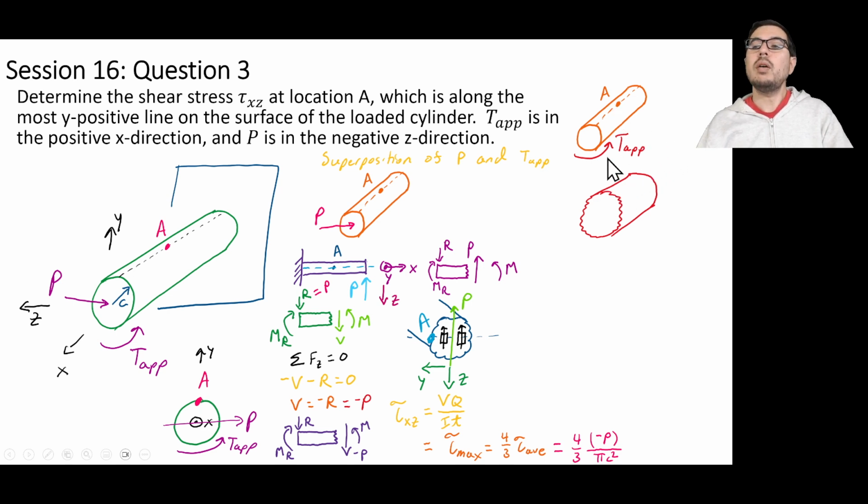And we also can think about the reaction force on this side, on the back side, because I'm going to have that reaction force on this back side, and that's going to affect the internal, did I say force? I mean reaction torque, the internal reaction torque that I'm going to have, or the internal torque that I'm going to have when I get to that slice. So the reaction torque here is TR, and you can see that that goes against Tap, and that same TR that I have here is acting on this system here, but this is sliced.